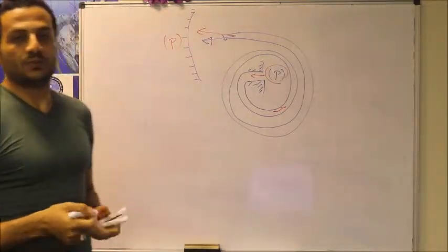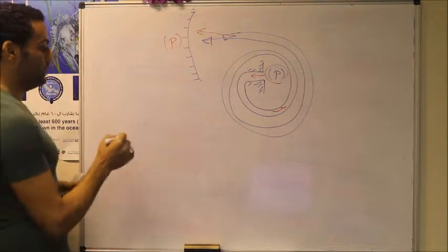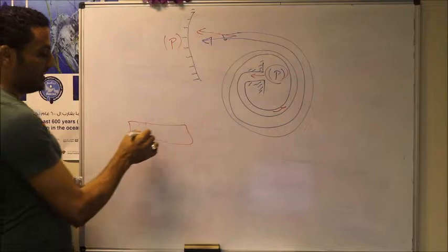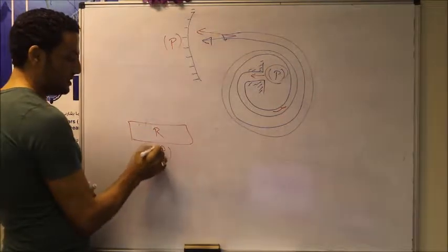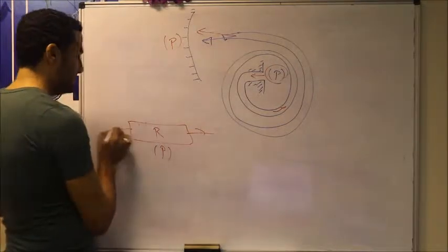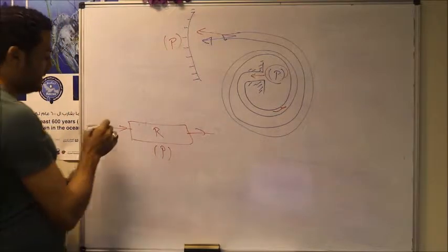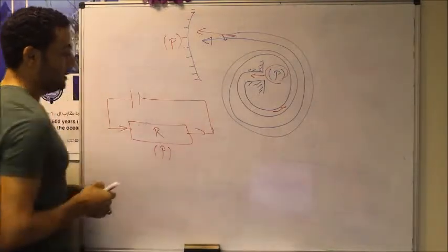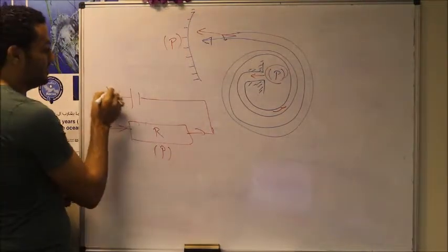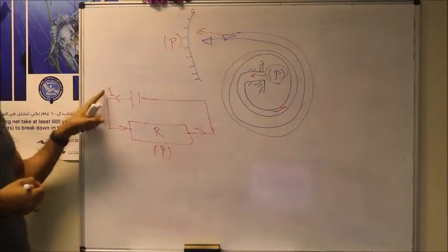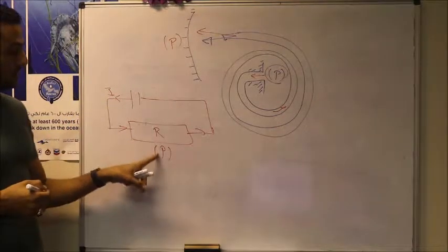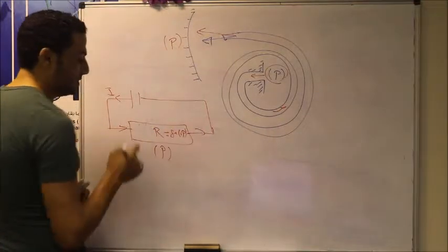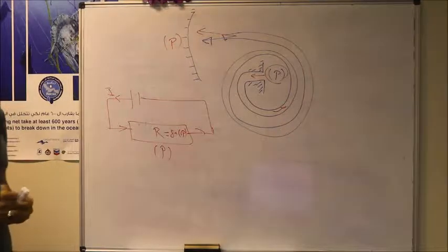Also we do have what's called the pressure transducer. The idea of the pressure transducer is that we do have a material with variable resistance, so when it is subjected to pressure, this resistance will vary. In this case we can connect this to an electric circuit. We can apply here a fixed amount of current. So the current is fixed and we know this value. And this resistance is a function of the pressure. This resistance varies depending on the value of the pressure.